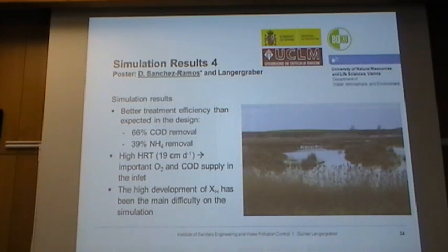These systems are designed with a very high hydraulic loading rate. That's a mistake on the slide. It should be hydraulic loading rate and not retention time, because there's quite a lot of flow through the systems that has to be treated. This was one of the main concerns. And this is a picture of the natural wetland, how it should look like when there's water.